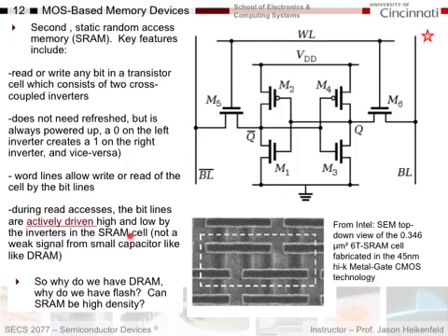And so before with DRAM, I had that little capacitor, right? And that capacitor had a little bit of charge on it, and it goes through the transistor, and it's got to basically charge up and get the signal out this really long line out that goes out the memory chip. Well, you could imagine that that might not be very fast, or it would be weak, because once the capacitor runs out of charge, that's all the charge you have to try to read out of the system. In this case, I have a powered transistor driving the charge onto the line, which is more powerful and can be faster. And so I can get faster speeds with this.